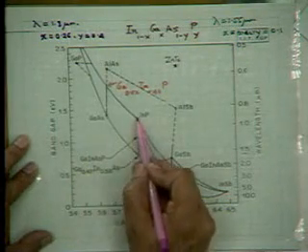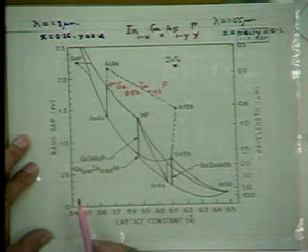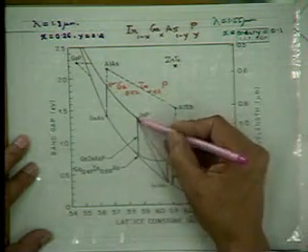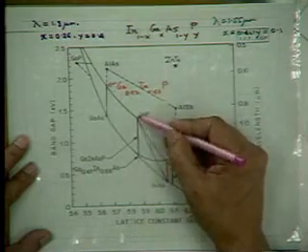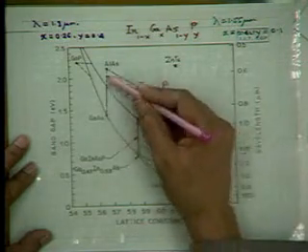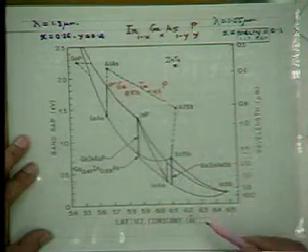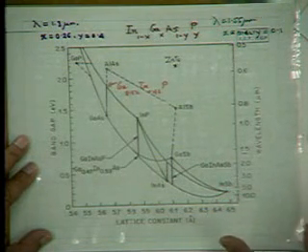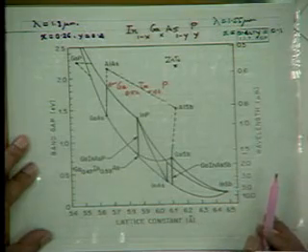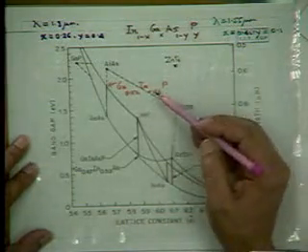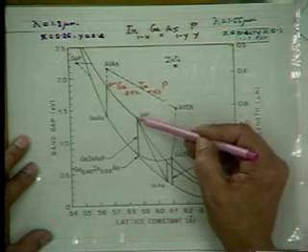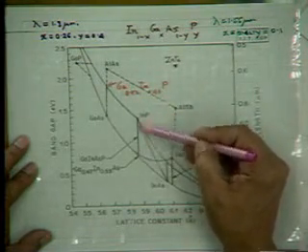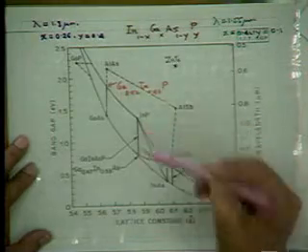So all active layers are based on single crystal epitaxial layers which are grown on substrates with matching lattice parameters. Of course, recent developments have shown that we can grow strained layers with slightly different lattice parameters, but the basic thinking is that we have to take substrates such as indium phosphide and grow lattice matched or nearly lattice matched layers on this.